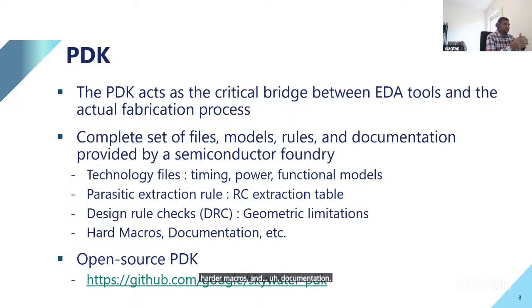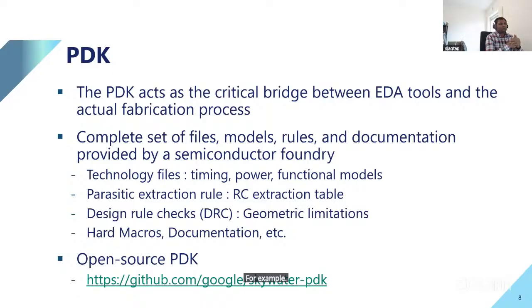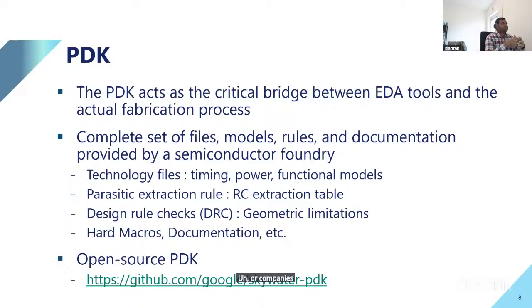Hard macros: the foundry will not provide you only registers and AND gates or combinational gates. It can provide you a lot more things, for example memories, ROMs, and custom analog blocks such as oscillators and amplifiers, you name it. A foundry doesn't design these itself. Other companies, like ARM or companies like us, will develop, for example, an A to D converter.